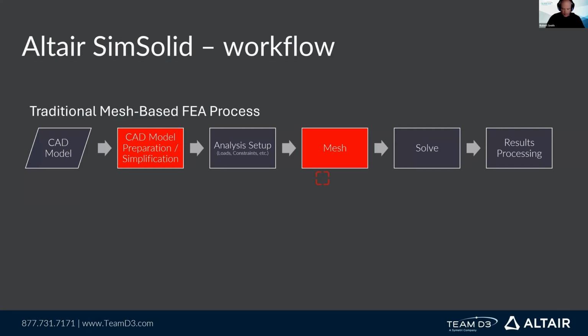for the analysis. When we're talking about the geometry input for a simulation, we're not really talking about a CAD model. Typically, we're talking about a mesh, and we use the CAD model to generate the mesh. And then we'll solve and we get to the results processing, which is ultimately our end goal: what is the predicted performance of our product.